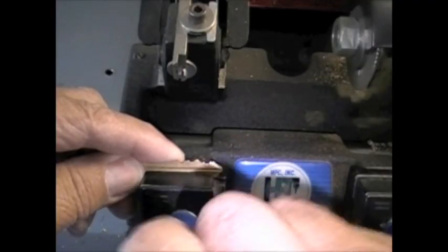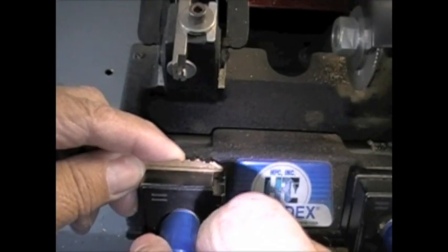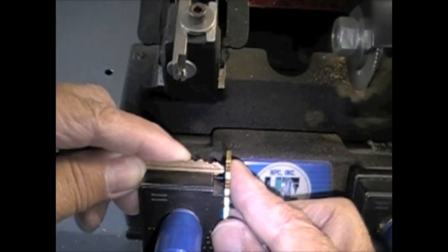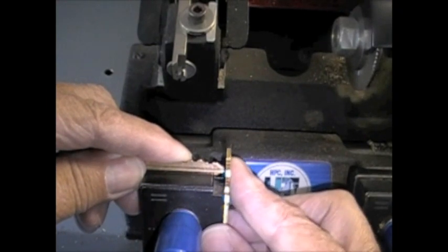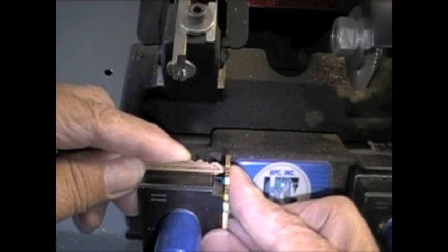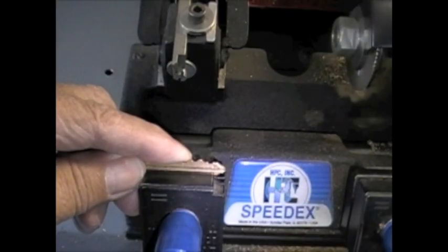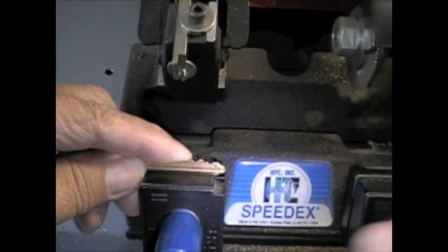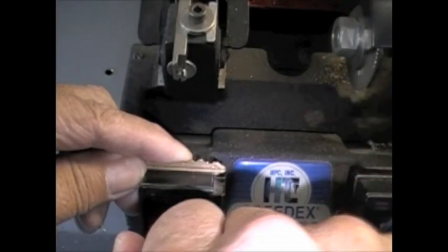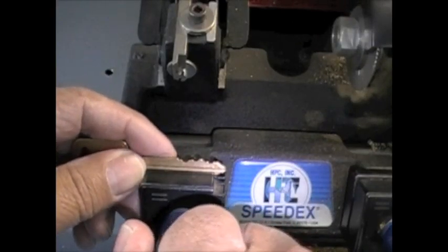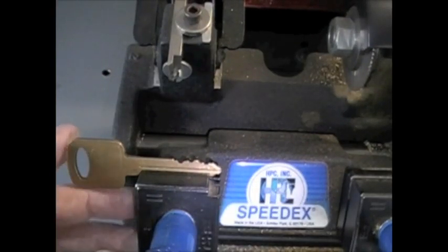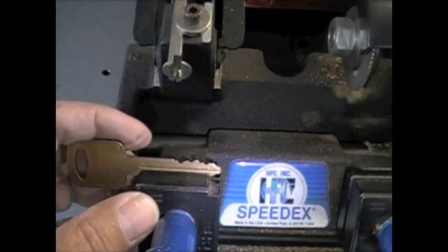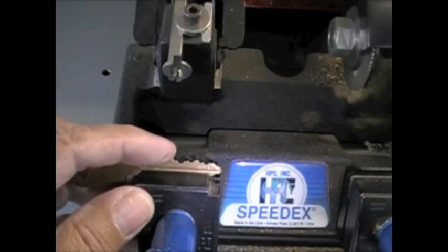Again, this is a tip stop key, so once you've got it about tight enough, take a key, put it on the block, and make sure it's pushed up all the way to the stop that I'm using, with this ridge flat against the top of the block, and then I tighten that up. At that point I want to tighten that good. And again, whatever key machine you get, read what the manual says and see if they recommend a specific side of the block for automotive keys or for tip stop keys.